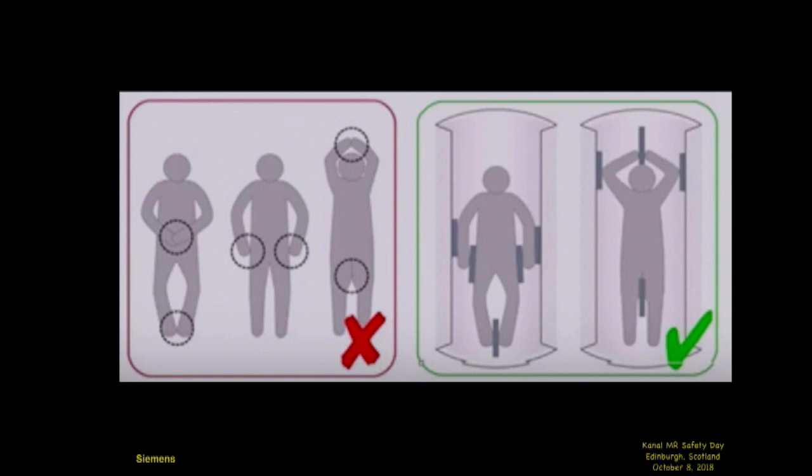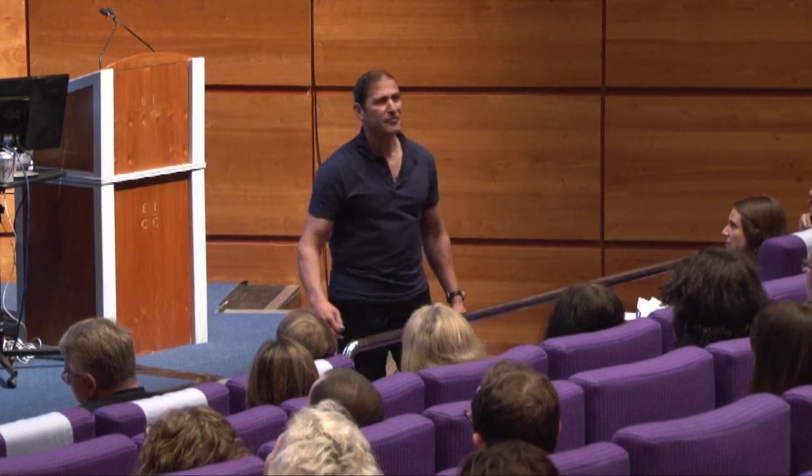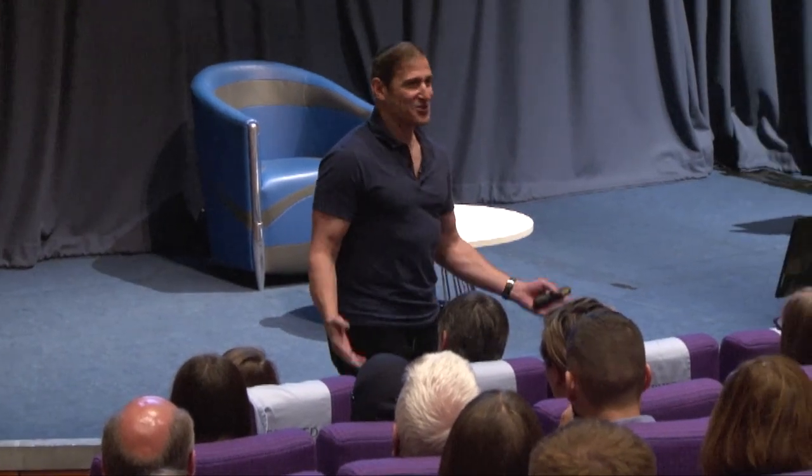People say that we've got cases reported to the FDA. They testify against themselves. They say, I was certain to use a sheet between the patient and the magnet wall. It's another type of burn. They want these to be non-electrically conductive loops. So the pads are there to give you distance and to give you resistance. And listen to them. They know what they're saying. Use the pads.